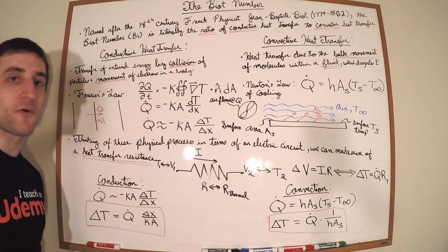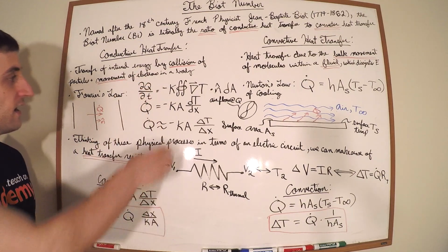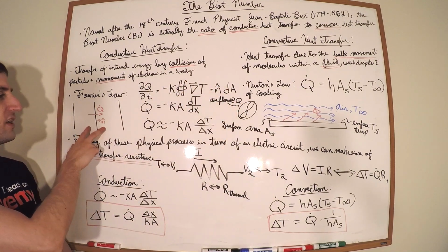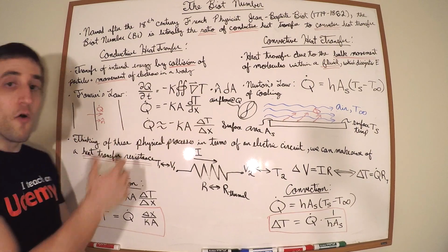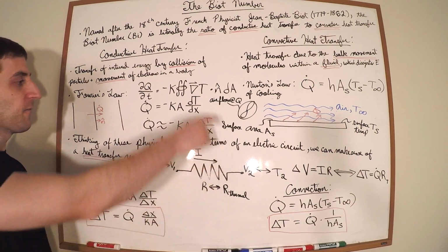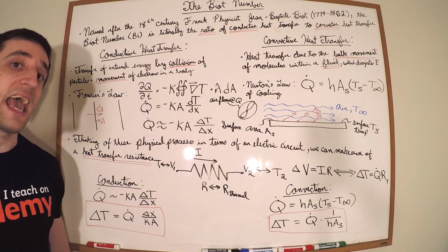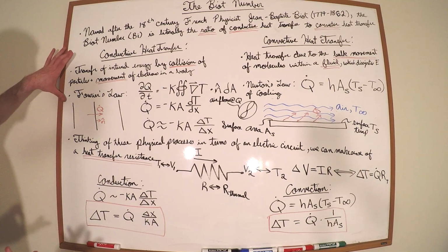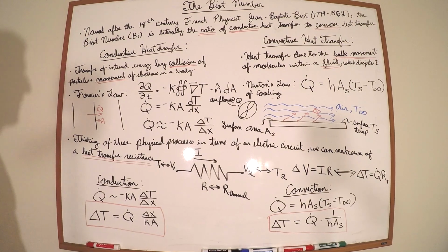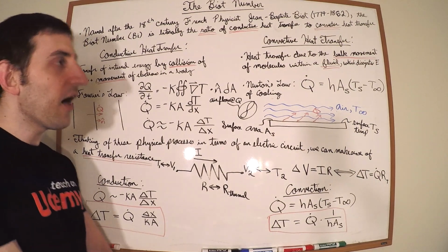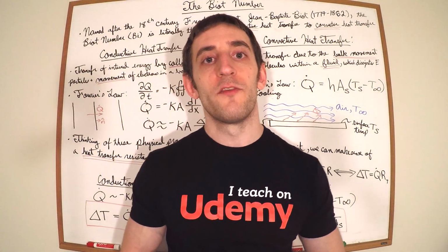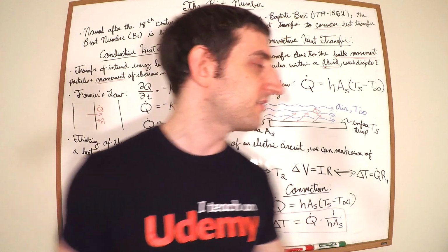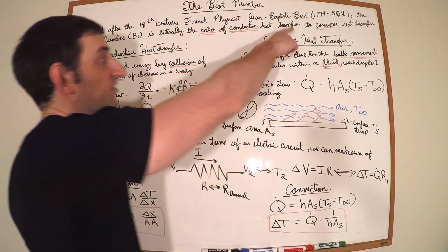So we can also approximate this by saying, okay, we can approximate that derivative. It's approximately the temperature difference between those two objects over the length over which it's flowing. And if we approximate it as such, we still can get reasonable answers, okay? So this is conductive heat transfer, just a brief overview, very quick, so you have some background on that. The other mechanism that is usually used for transmitting energy and transferring heat across different objects is convection, okay?